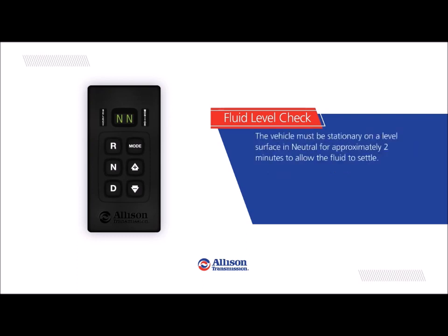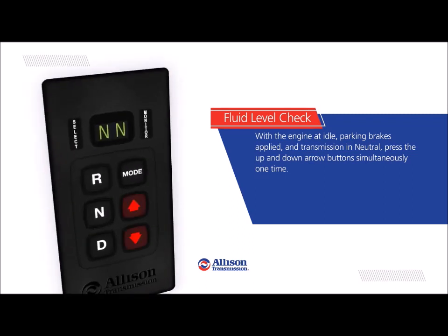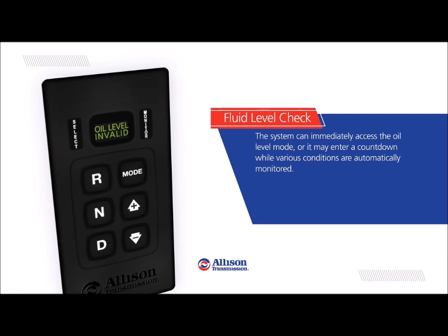The vehicle must be stationary on a level surface in neutral for approximately 2 minutes to allow the fluid to settle. With the engine at idle, parking brakes applied, and transmission in neutral, press the up and down arrow buttons simultaneously one time. The system can immediately access the oil level mode, or it may enter a countdown while various conditions are automatically